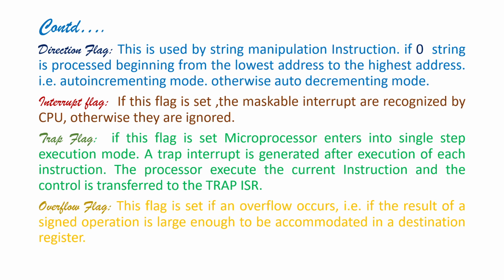Overflow flag. This flag is set if an overflow occurs, that is, if the result of a signed operation is too large to be accommodated in the destination register.